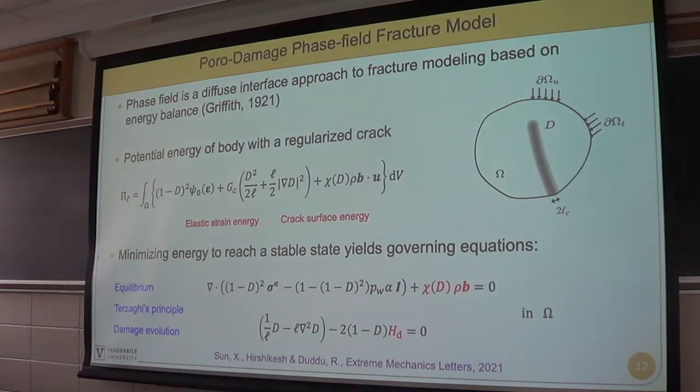So the phase field framework goes back to this energy-based approach for fracture that was proposed in the 1920s by Griffith. And it's a diffuse interface approach to fracture. That means, let's say you have a body and you have a crack. Typically you interpret that crack as a sharp interface that is separating the body into two pieces, correct? But in the phase field, what you're doing is you're not representing it as two surfaces, because then you have to do a lot of algorithmic changes to represent those two surfaces.